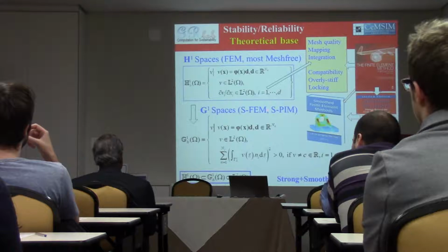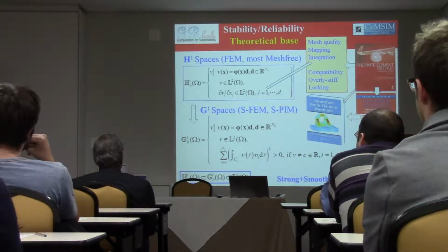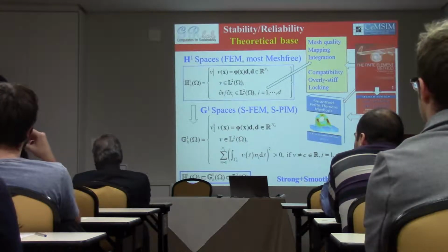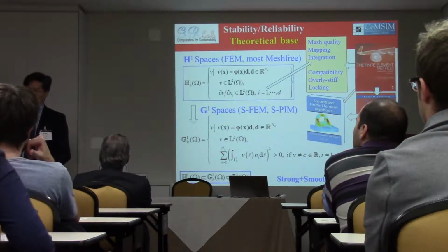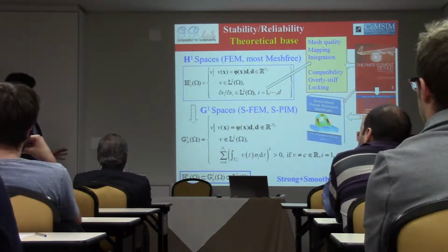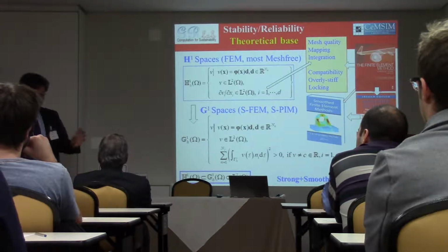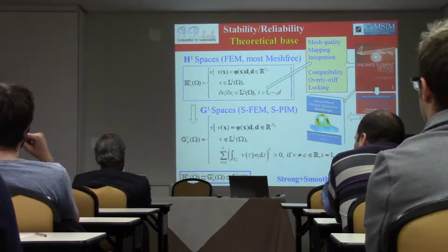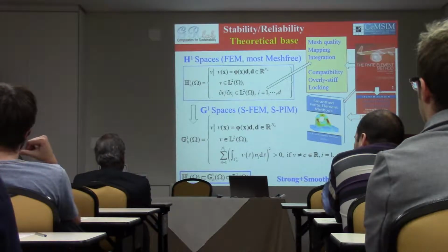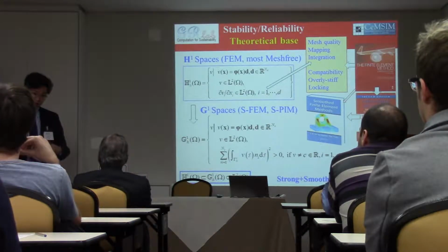By doing so, I actually didn't perform any differentiation on the functions. What I do is an integration. This basically means the requirement on the function I create to build my numerical model is reduced. It's weakened, further weakened. That's called weak formulation. By doing so, what I am able to achieve is that you can now use triangular elements, and triangular elements can work as well as quadrilateral elements.